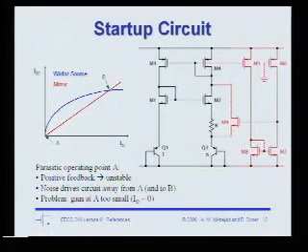All right, so now this problem with the startup. Let's look at that real quick. So this circuit here is going to somehow detect that there's no current and do something about it. So let's assume that there is no current in M4, right? Let's say that unfortunately we turned on our power supply and it went to this point A. Well, if there's no current in M4, that means there's no current in M5, right? And that zero current gets mirrored over to M7, and so M7 is operating with no current. M6 is essentially just a resistor. Let's say it's a long channel PMOS device, it's a resistor.